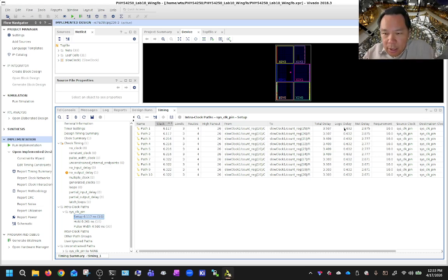Each of these logic gate steps is expected to have 0.6 nanoseconds of delay, and depending on how many steps it needs to get through, it multiplies that and figures out the delay at this point, of 3.5 nanoseconds because of the logic. And there's also the propagation. The net means the wire. You add these together, and I think that's how I figure out the 6.2 nanosecond delay. That's the maximum that we'll get on this particular design.